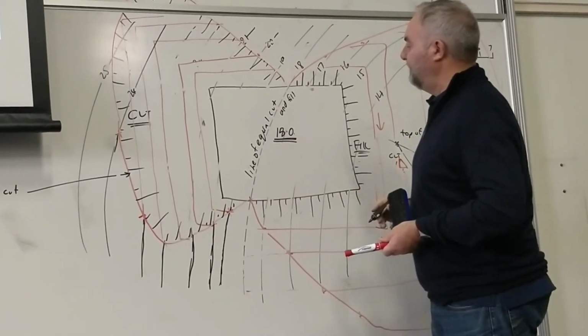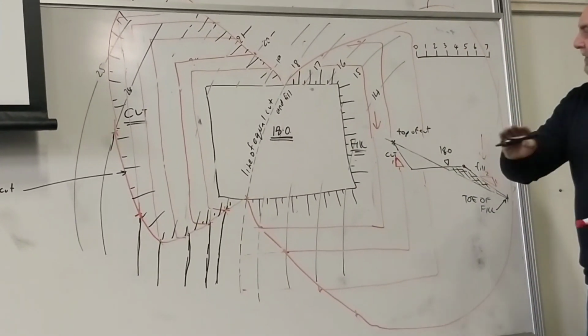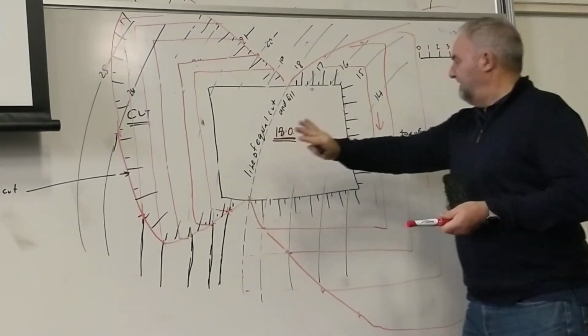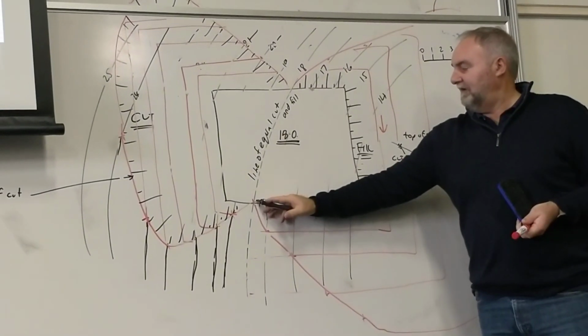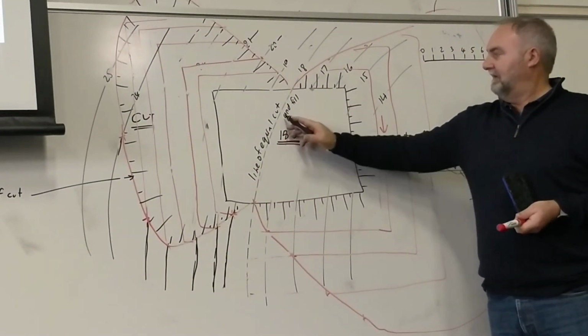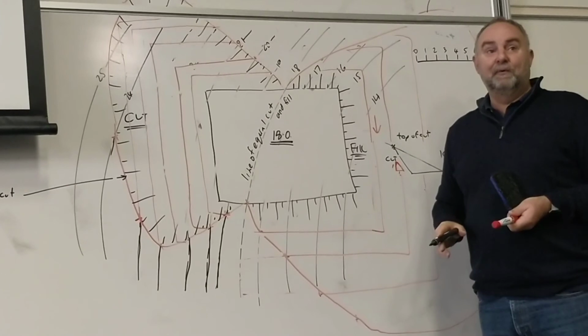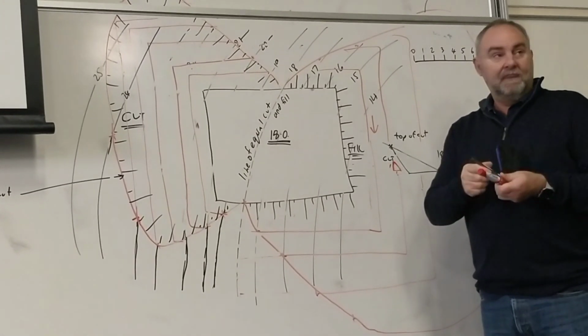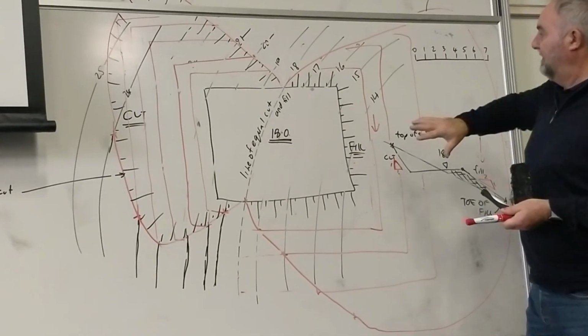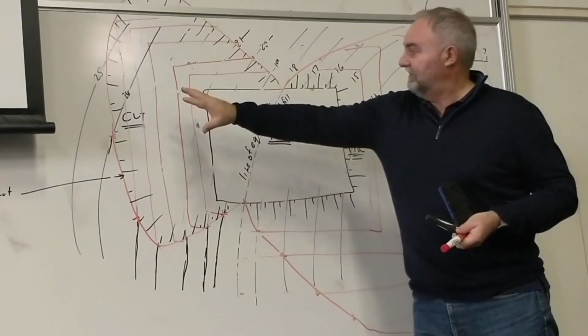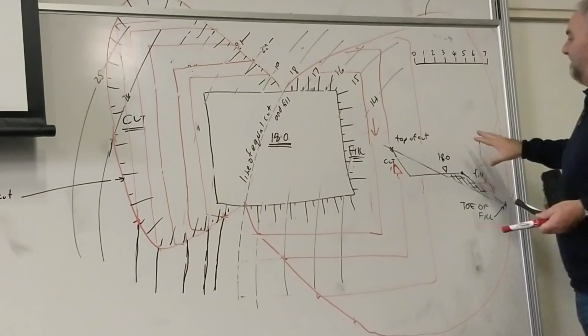Technically, if a digger driver was coming out and he was cutting away this area and filling up that area, the only piece of grass left that you'll see would be this little bit here. Or if they were in clay, the only little bit of original ground would be that line. It also helps determine in plan view where the cut is and where the fill is.